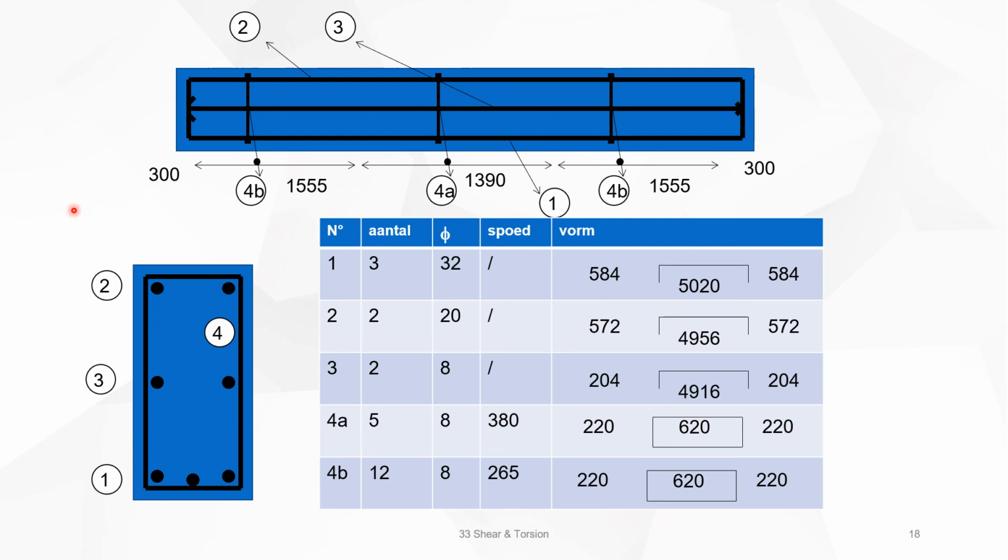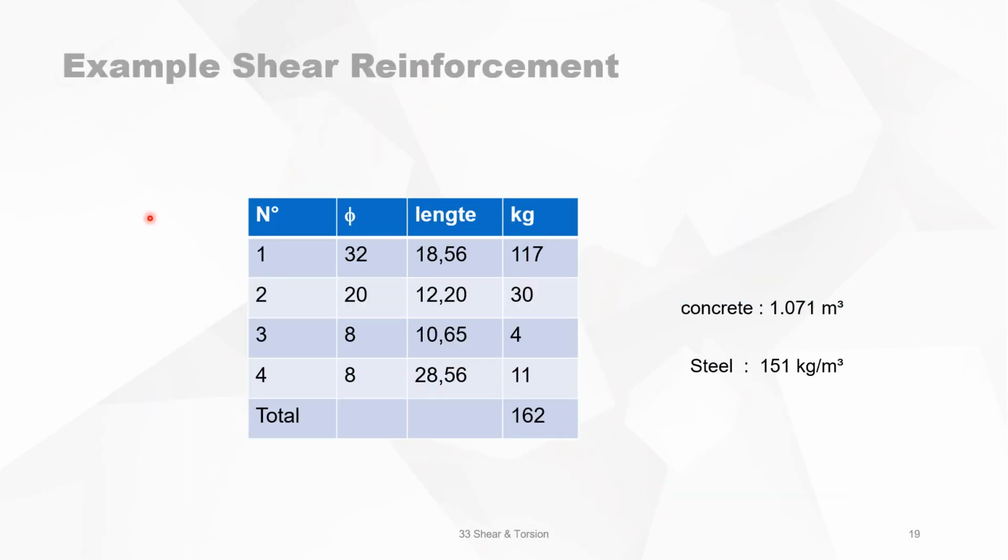And then this is a total drawing where we end. You have the tension reinforcement, compression reinforcement, technological reinforcement. You try to make this distance always smaller than 300 millimeters. You have the bending schedule, and at the end you can make a summary of it, where you calculate the total volume and weight of concrete and the total weight of steel used.